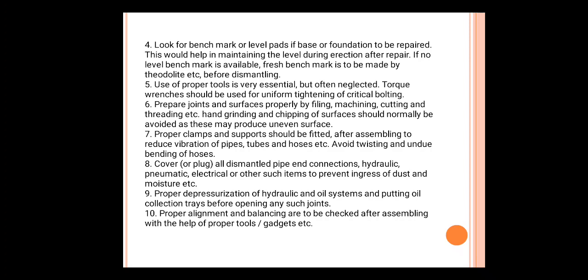Seventh, proper clamps and supports should be fitted after assembling, which reduces the vibration of the pipes, tubes and hoses, and avoids twisting and undue bending of the hoses. Eighth, cover all the dismantled pipes and connections, hydraulic, pneumatic, electrical and other such items, to prevent ingress of dust and moisture.